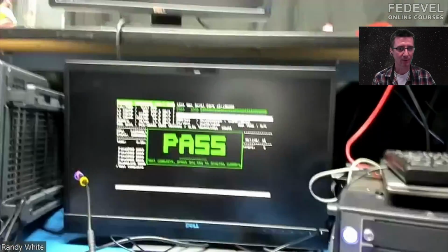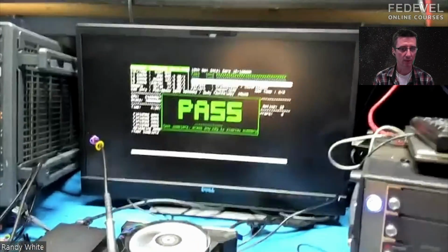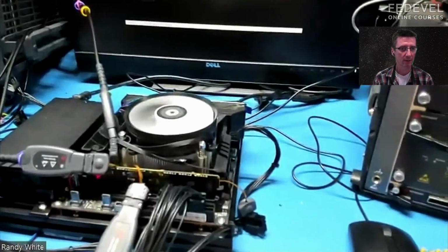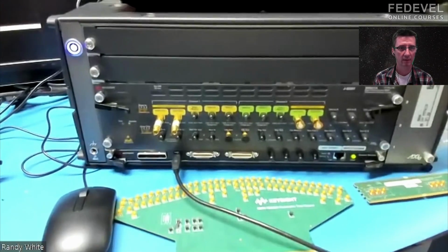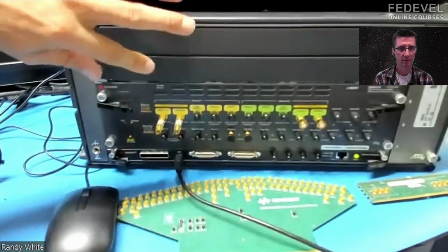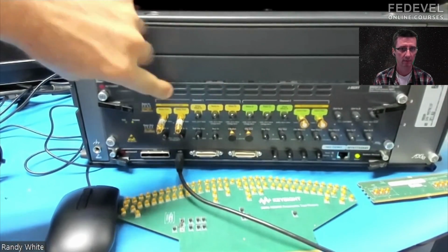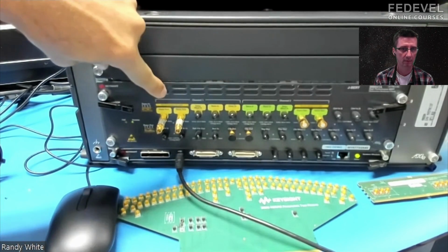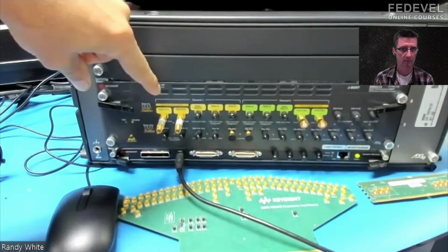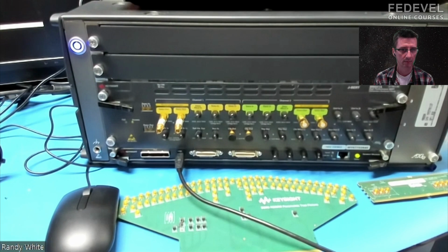Okay, about the device on the right, if I understood correctly, that device is to measure memory chips, or it emulates the controller? Yeah, this one. That's right. Okay. So here on the front panel, you have this yellow section. This is a channel. So we have data out, plus and minus, data in. So output, input. So we're sending a test signal out and then somehow the device is in a loop back state.